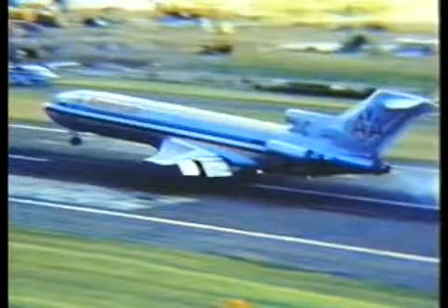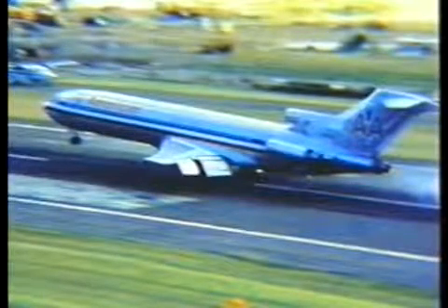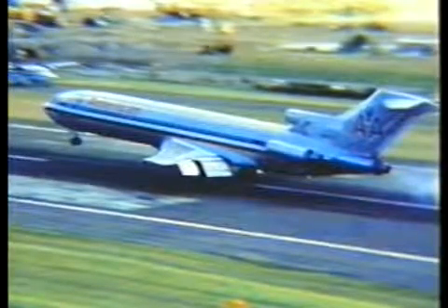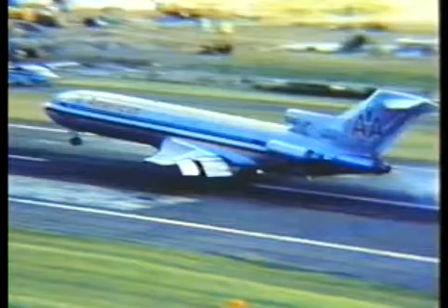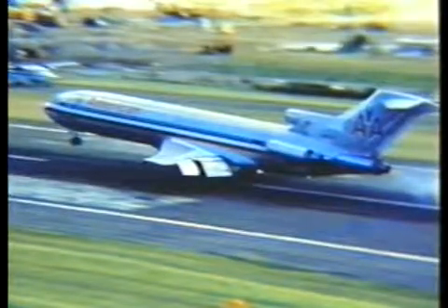Braking effectiveness drops radically when tires skid, not to mention damage done to the tires themselves. Larger aircraft are equipped with anti-skid equipment that, when working properly, assures that the wheels can't be locked and the tires won't skid. By the way, intermittent braking serves no useful purpose when the objective is maximum deceleration, because the periods between maximum brake application produce only slight cooling.